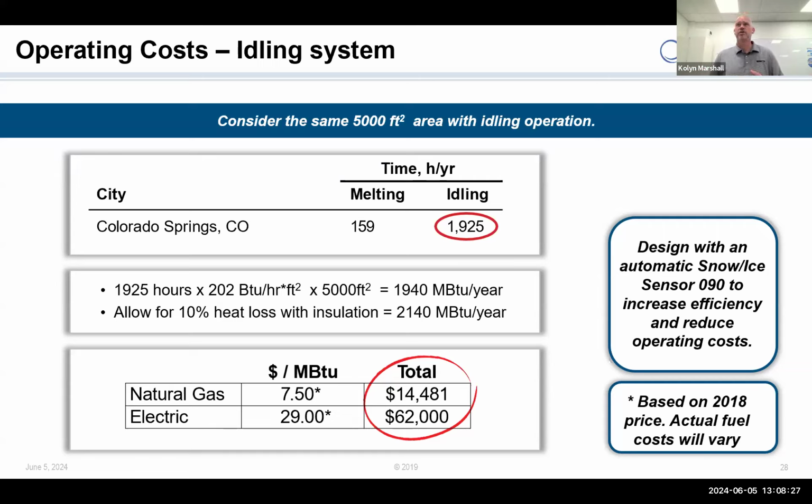They tie into the freezers and they reclaim that heat for the portico. We do ice rinks. They're extracting heat out of the ice, and that extracted heat is being vented. Well, if you throw on a reclaim unit and you capture it, you can run a snowmelt system, right? So there's a lot of systems that will idle and will run 24/7 on free energy. So it's still done, but really preemptive systems are the ones that we see more of.